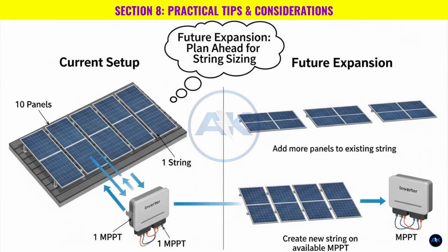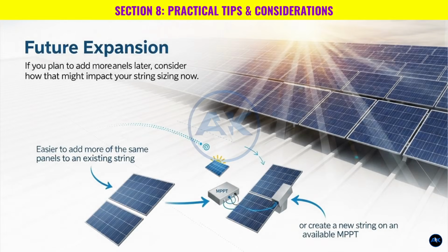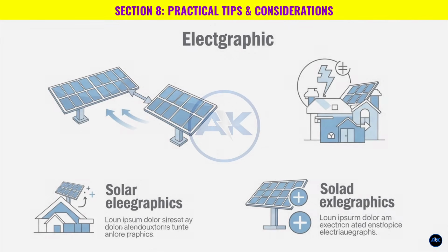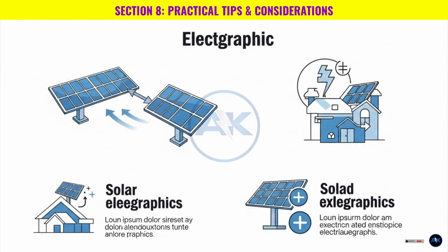Future expansion. If you plan to add more panels later, consider how that might impact your string sizing now. It's often easier to add more of the same panels to an existing string or create a new string on an available MPPT.